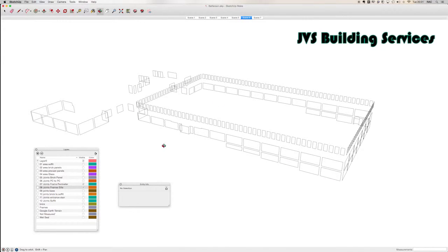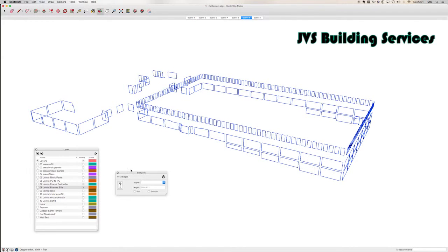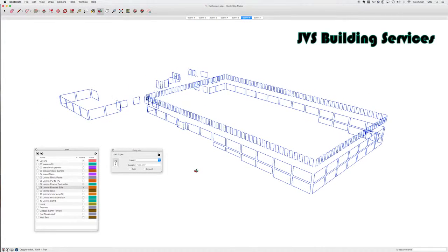First, you turn all the layers off but the ones that carry one work element. So this particular work element is all the window and door frame perimeter joints. And then if I select them all, I can see that there's 7,592 lineal feet of that kind of joint. The cost to restore those joints is that number times the unit cost of between $4 and $5 per foot. So it would cost about $38,000 to replace all the perimeter joints on this building.